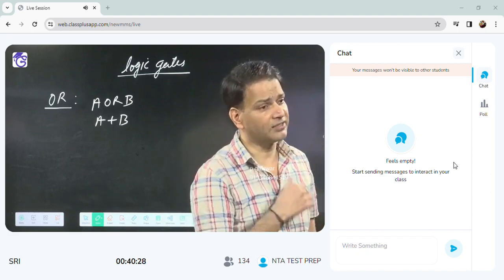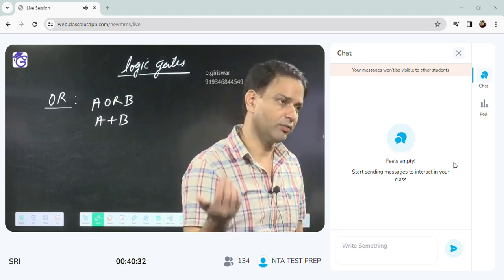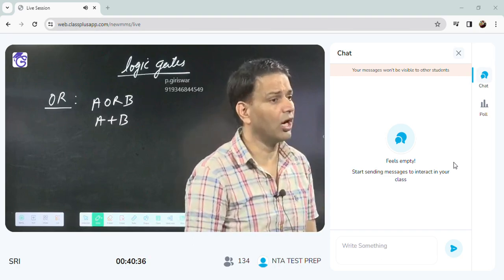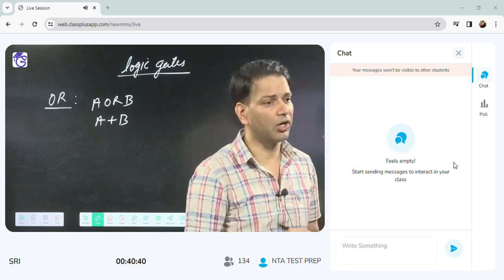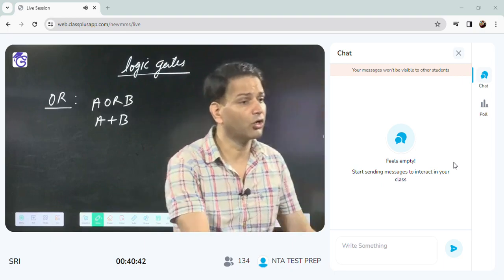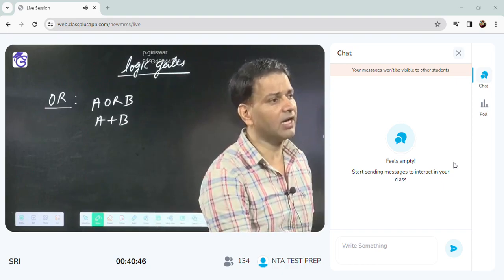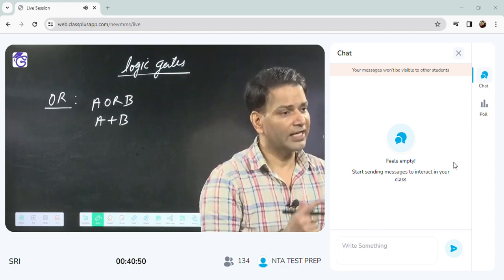Like A is 1, B is 0, output 1. A is 0, B is 1, output 1. Both are 1, output 1. Only in one case will we get a low output, when both are 0. So that is the meaning of the OR operation: for A or B, if anyone is high, then the output will be high. Okay, the next operation.